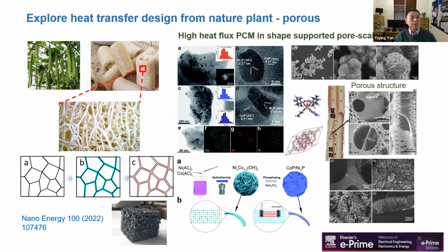Recent effort has been focused on improved PCM applications for high temperature thermal management, such as applied to the solar farm with a solar salt, like 60% sodium nitrate and 40% potassium nitrate as a PCM, and silicon carbide ceramic as a porous mesh to improve the property against corrosion. So nature-inspired solutions have been explored, and the effectiveness of shape-stabilized PCM to enhance heat transfer.